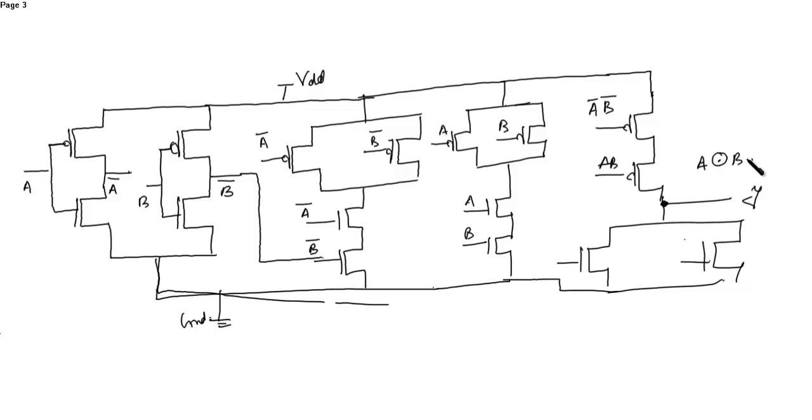So now you can see it's too complicated to draw the twisted schematic of this and then the layout. So what we will do, we'll draw the layout from the schematic by using the transmission gate. So let's see in what way you can reduce this number of PMOS and NMOS. This can be done by drawing the schematic keeping in mind the truth table of the XNOR gate. So you can write it as schematic from truth table.